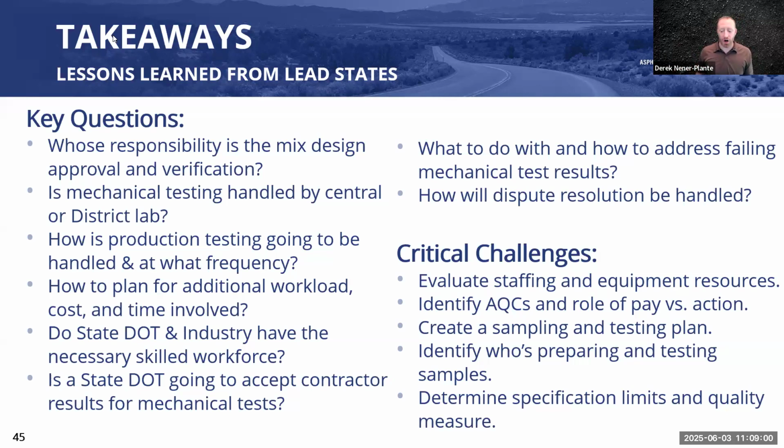And then obviously determining spec limits and a quality measure, which all depend certainly on your validation, but also on what you're trying to get out of it. Are you trying to measure variability, etc.? Also dependent on how often you're sampling and testing. So these are at least a list of the questions and things that need to be thought of. If you're thinking about a criteria set for mix design, you may not just grab that value and bring it into production. There are these other questions you start thinking about that affect that criteria and those spec limits as well. So, all things to think about.